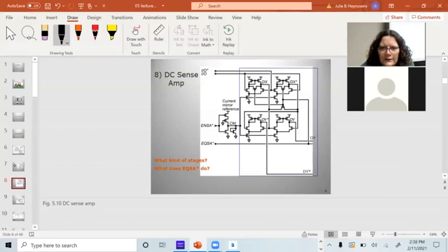And if we look at the gain transistors here, these are the gain transistors there and there. They're all NMOS, so this is 4 N-flavor diff amps. They're not directly in parallel, which is the reason why there's 4 of them.